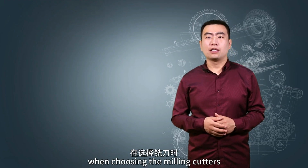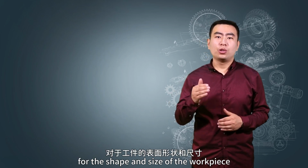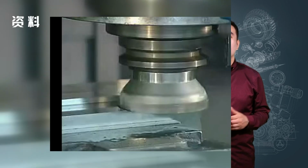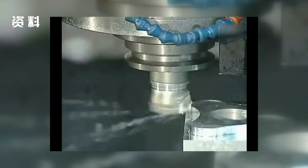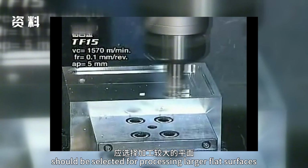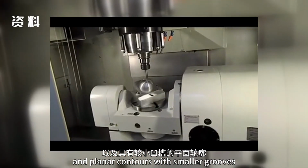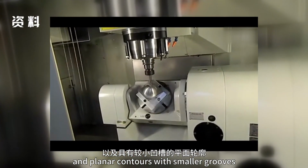When choosing the milling cutters, the type should be suitable for the shape and size of the workpiece. Face milling cutters should be selected for processing larger flat surfaces, while end mills should be selected for machining step surfaces and planar contours with smaller grooves.